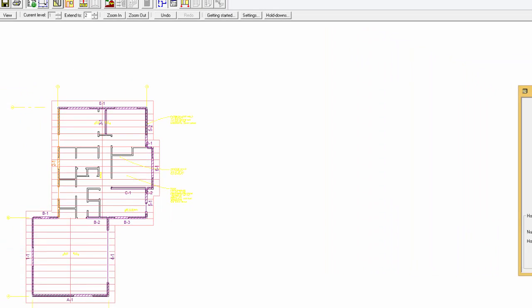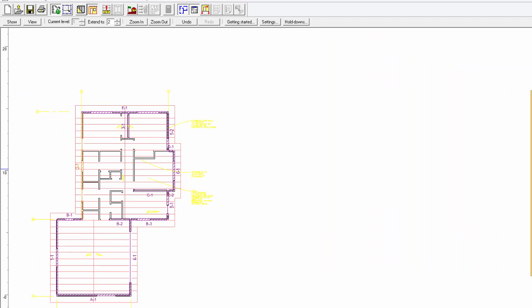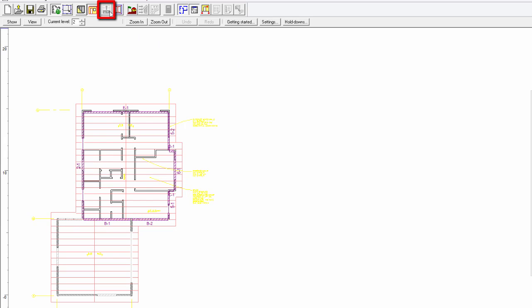Once satisfied with the openings on the first level, click on the Extend Walls button. This automatically creates the upper level walls for the blocks with multiple levels. This also recreates the openings on the upper level, therefore some openings might require some adjusting.